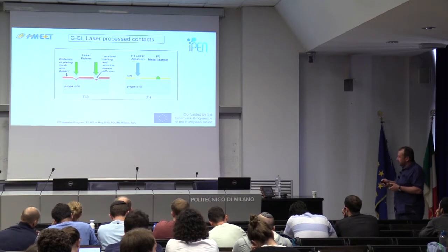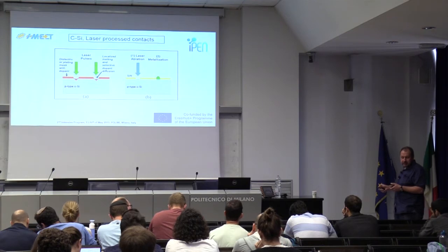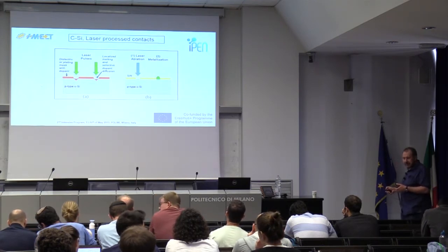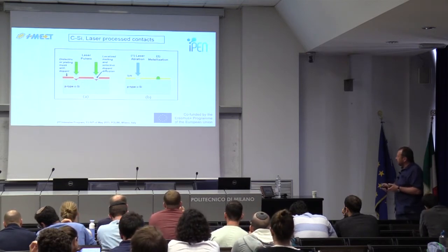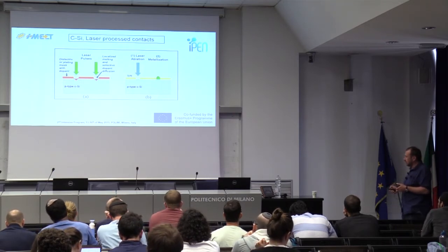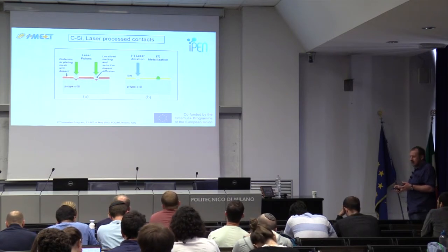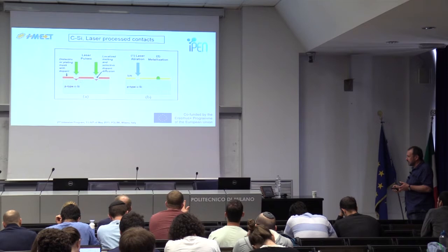One more option is laser processed contacts. So in the first case, shown in the left figure, a dopant material is put. It may be sprayed on the top surface of a silicon cell, and with laser pulses, they may be. This does not have to be a femtosecond laser or long pulse laser. Enough, it has to melt this material, which brings the dopant into the silicon cell, and it remelts silicon together with this covering layer, again increasing the doping concentration locally and improving the contacts.